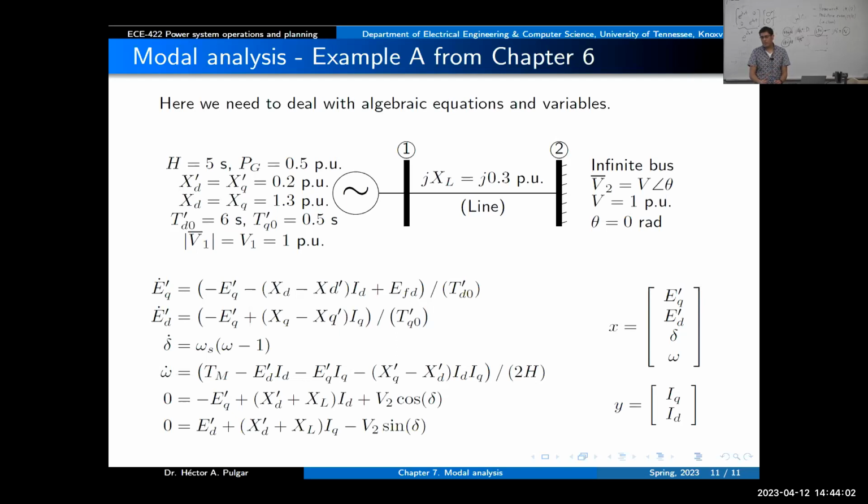The derivative of the speed is going to be related to the negative of that angle, right? The derivative of the angle is going to be related directly to the positive of the speed. So that will create that shifting of 90 degrees. The speed will be leading the angle by 90 degrees in a machine.